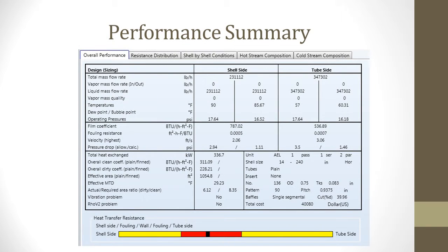And here we can see a performance summary with a total heat exchanged of 336.7 kilowatts, which is pretty close to our initial guess, and also at the bottom a heat transfer resistance graph that shows the resistance from shell side to tube side.